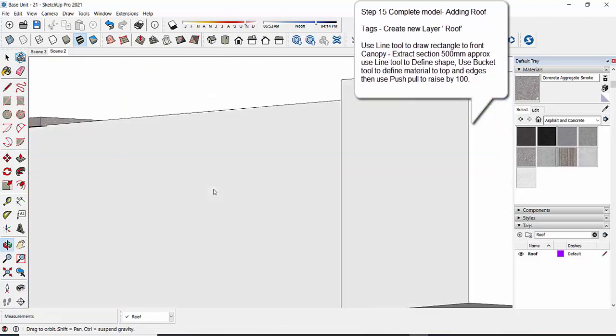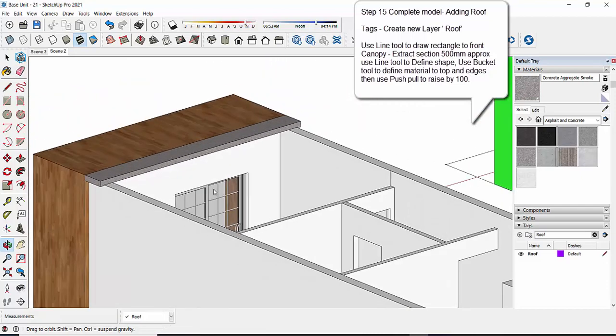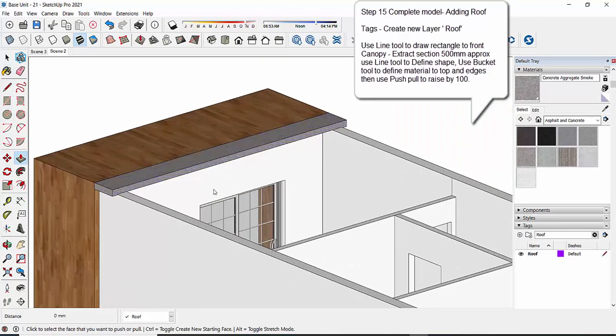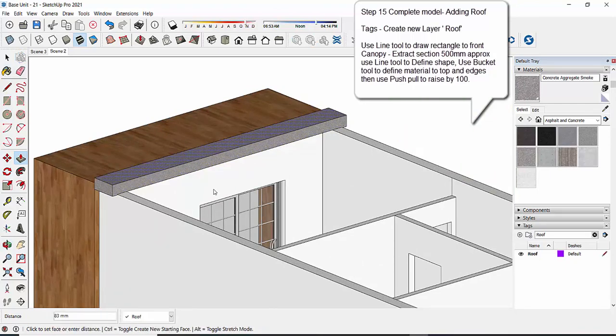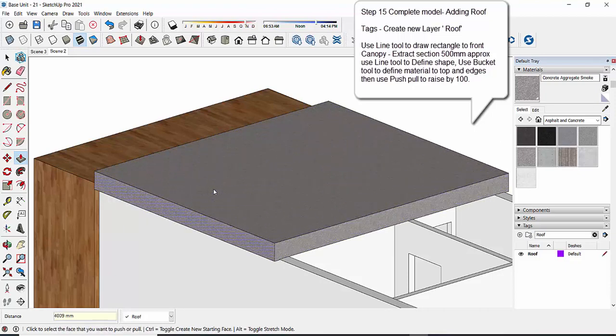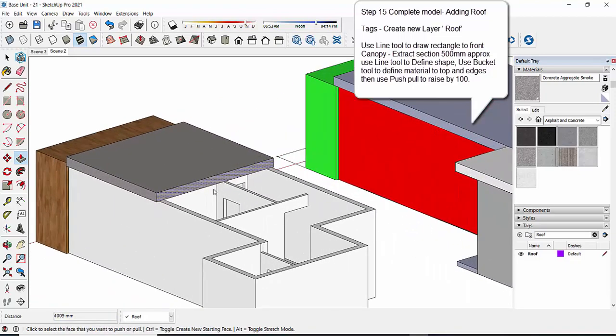And what I can do now is extrude the height a little bit, take it up from its existing thickness, so we can define what this is going to be. Let me add this by 200 millimeters. I can then drag and extrude it.